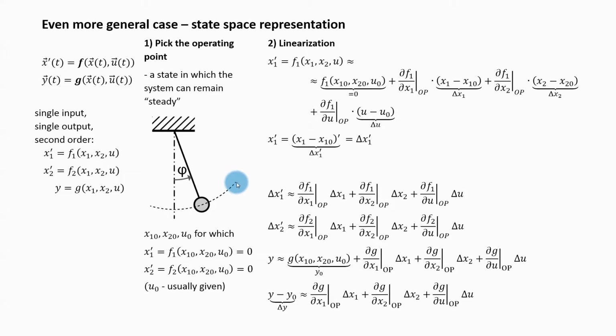Even if you moved your pendulum to this position at some initial time, the pendulum would immediately leave this initial position. Unless there would be some continuous force pushing it sideways, there is just no way the pendulum is going to steadily remain in a state that would keep it at this place or in its close vicinity. Consequently, if you picked this position for your operating point, the movement of the pendulum would not be just some small shifts around the operating point. Therefore, the movement of the pendulum would correspond to the large signal behavior, and any linearization around an operating point corresponding to this position would be quite imprecise and most likely unusable.